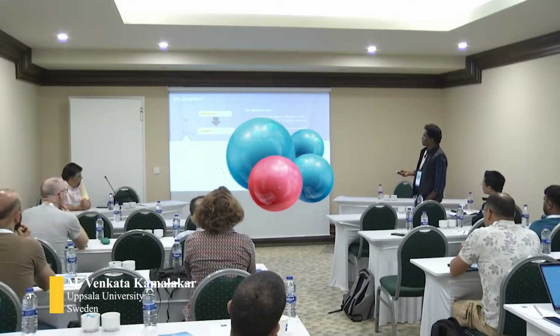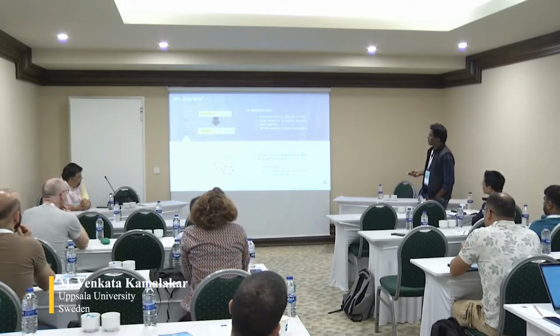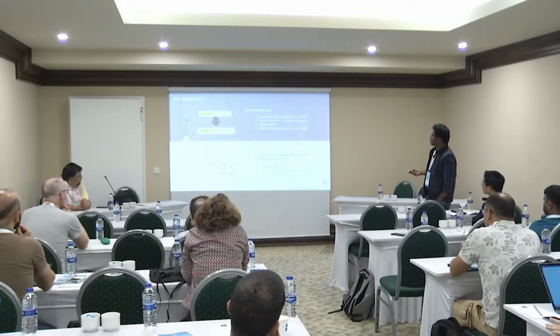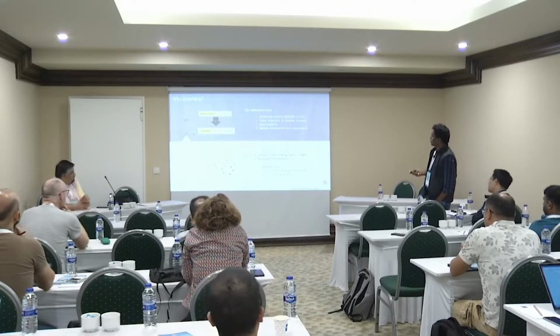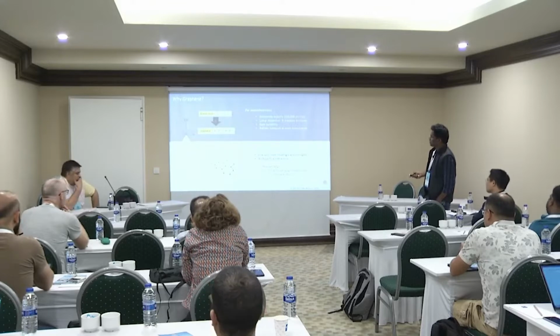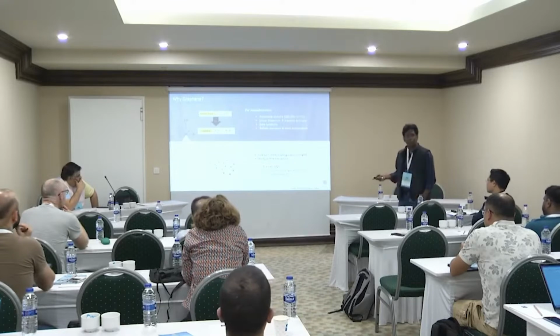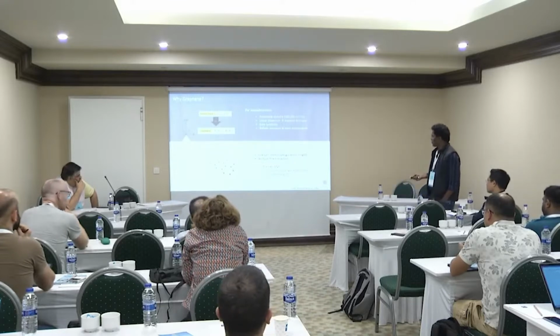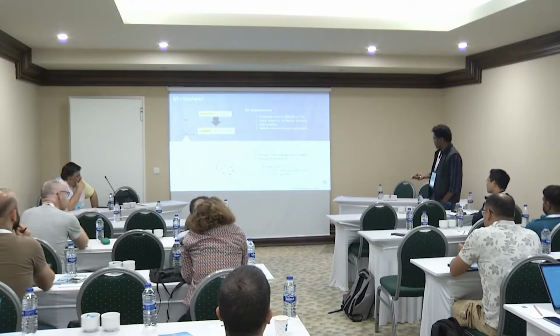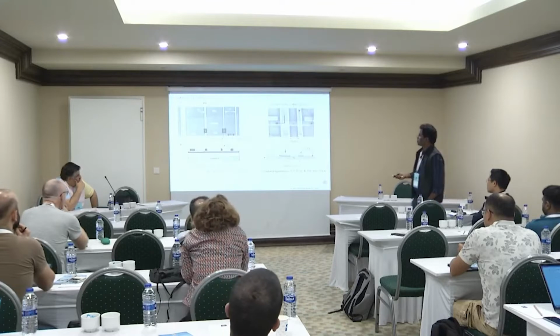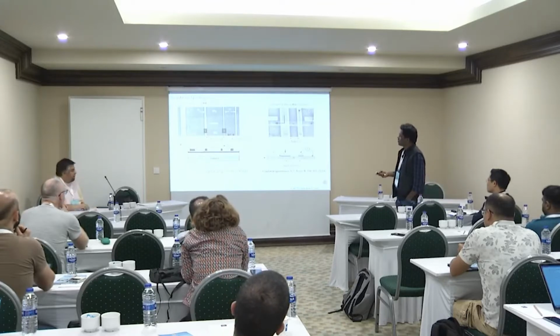So coming back to where we started with graphene, graphene is known for nanoelectronics because of high achievable mobility, because of its linear dispersion, gate tunability and ballistic transport. From the point of view of spintronics, these carbon atoms have very low spin-orbit coupling and no hyperfine spin interaction, which means that theoretically a very long spin diffusion length is possible with a very high spin lifetime.